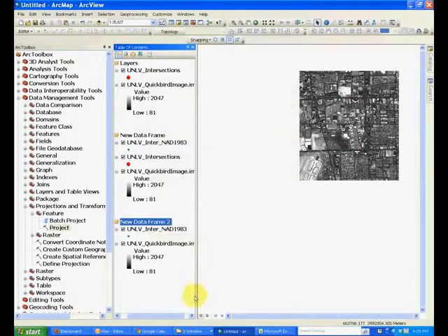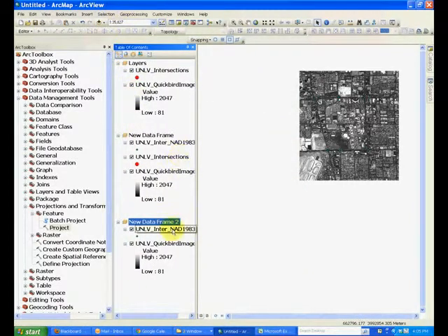So what you learned today from this exercise is that it matters how the two projections are. If they have the same datum and the same projection, then you will not get that warning, and the program will not have to change the coordinates on the go to make sure that you have the right image.